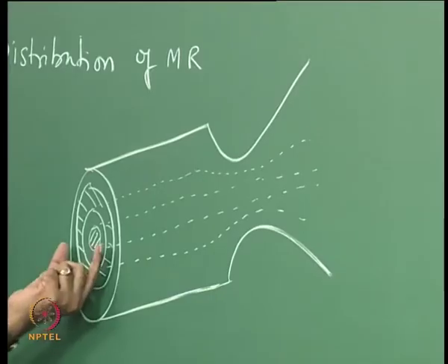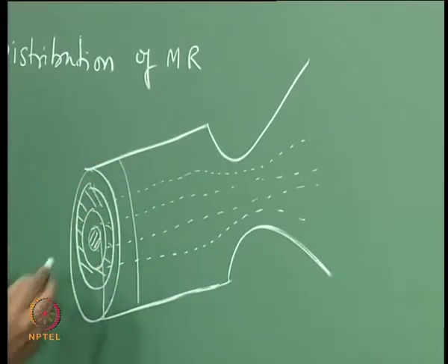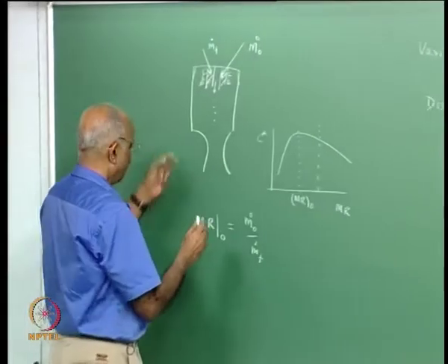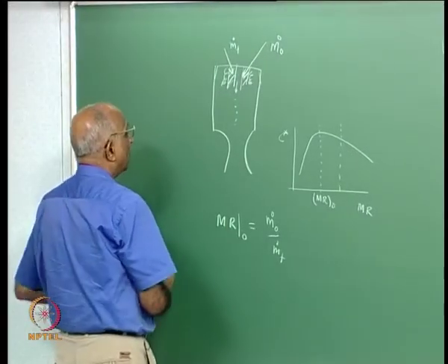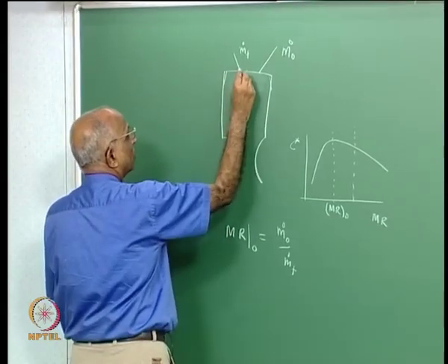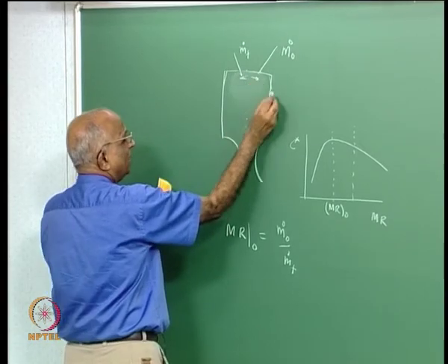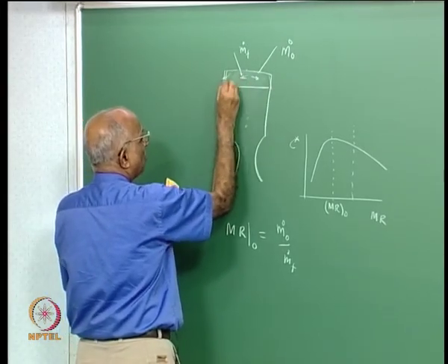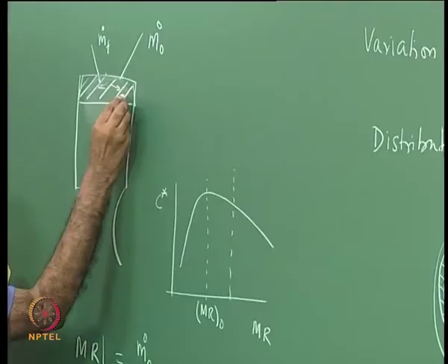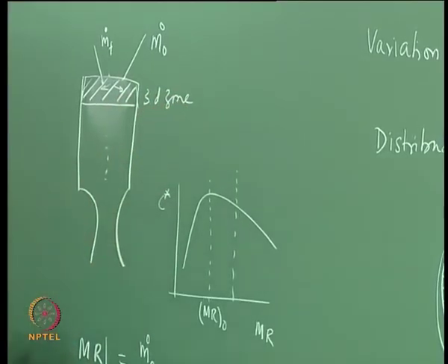And what would happen? I know as soon as I inject something it is highly 3-dimensional, like for instance let me correct this figure now for you. I inject the fuel and oxidizer into it. Initially the droplets are travelling in all directions, therefore I have a very strong 3-dimensional zone. And what do you mean by a 3-dimensional zone?